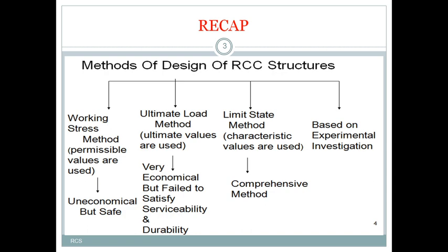Why is it safe and why is it uneconomical? The structures which are designed based on the working stress method give more cross-sectional area. The size of the section is larger, so I can say it is uneconomical. Because of the larger section, the structure will be safe.